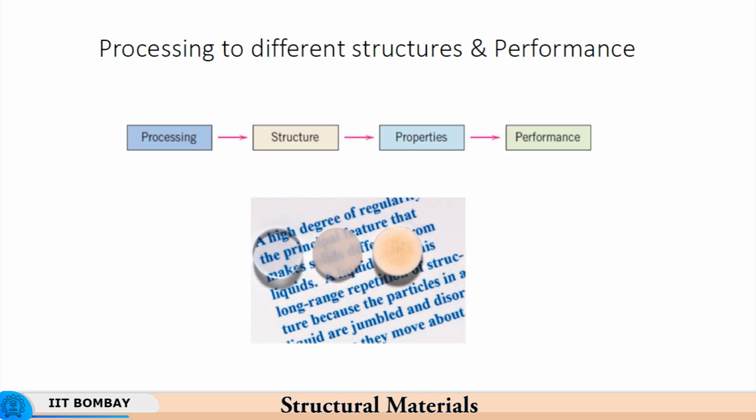So, you need to take care that there is some sort of shielding gas or atmosphere which is locally generated, which keeps out oxygen and lets in only those gases which do not react with iron when it is molten in particular. When iron is solid and cool, it does not react with oxygen, and it can get exposed to oxygen without any adverse effects.